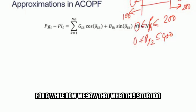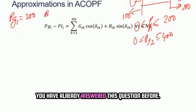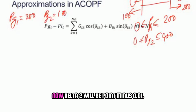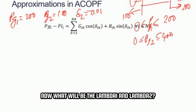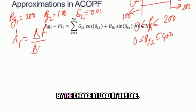Now we saw that when this situation is there, that means PG1 will be generating 200. You have already answered this question before. PG2 will be generating 100. Now delta 2 will be minus 0.01. This you have already told before, right? And everything is same. Now what will be the lambda 1 and lambda 2? So lambda 1 is the change in cost in the objective function by the change in load at bus 1.